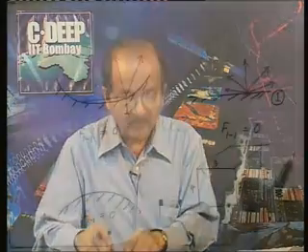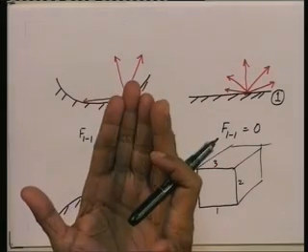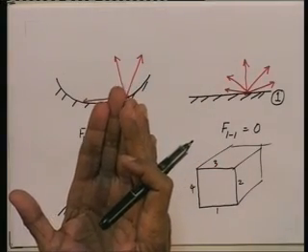Then it follows that surface 1 and 2, if I treat it as one surface, call it as say surface A, all right. It follows that for this surface A, which consists of 1 plus 2 together, 2 rectangles together with a common edge, the shape factor of surface A with respect to itself will be non-zero.